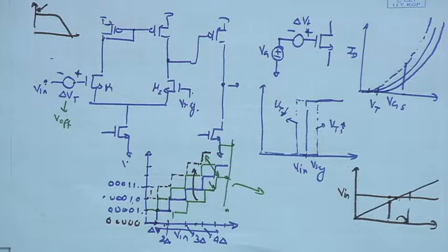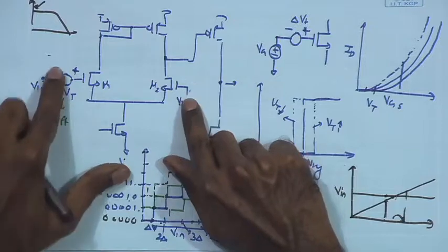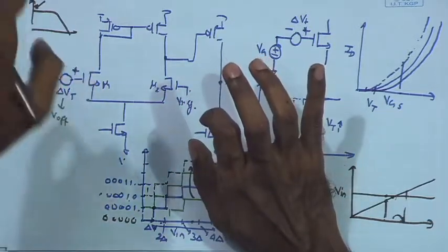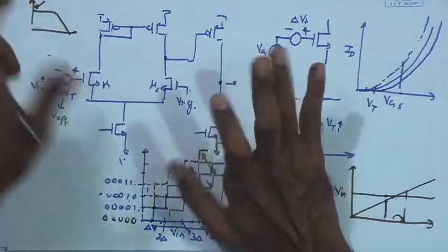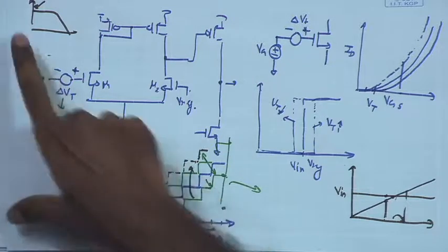So, we take a finite gm. In this case the DC point is the DC bias, and what you have is a small difference in DC between these two, which can be seen as DC bias plus that delta V. That delta V is small signal. What I am saying is small signal is applicable, and we are looking at small signal gain. So, small signal gain does not mean high frequency, small signal can be DC.